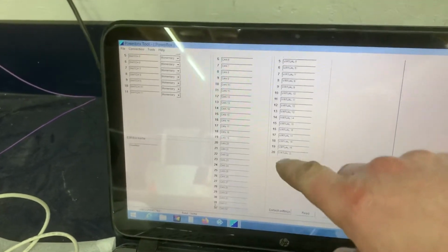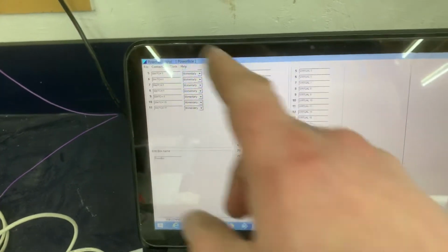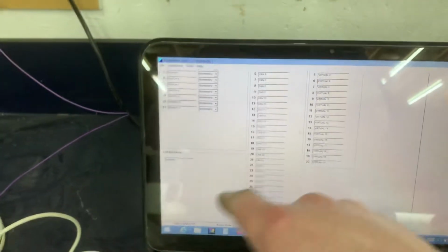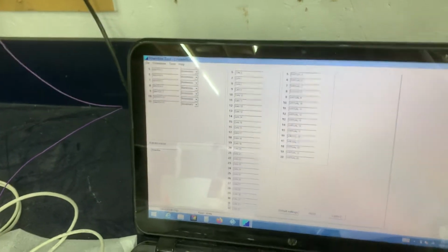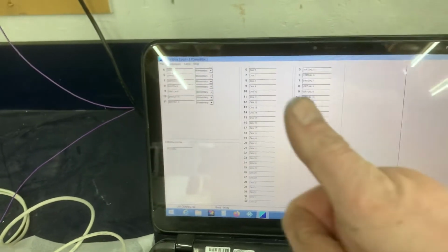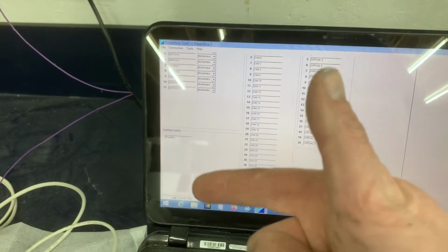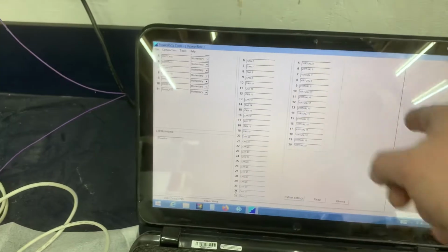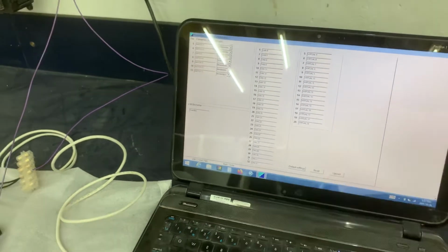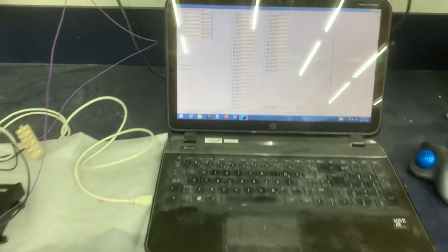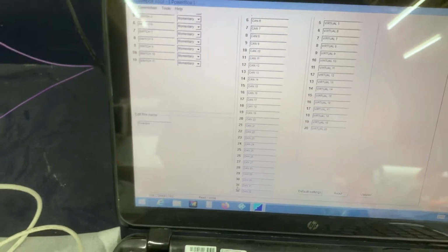So you basically create a virtual input that looks at: have you selected the fog lamps? Yes, so you'll see an actual input or a CAN input, because it'll be from the CAN-based keyboard. Is the fog light switch on? Yes. Is the dip beam on? Yes. Okay, then you can fire the output. But if the dip beam isn't on, if the high beam's on, it turns the fog lamps off at the front. So it's a decision-making process. So you've got 20 virtual inputs, so you can program.